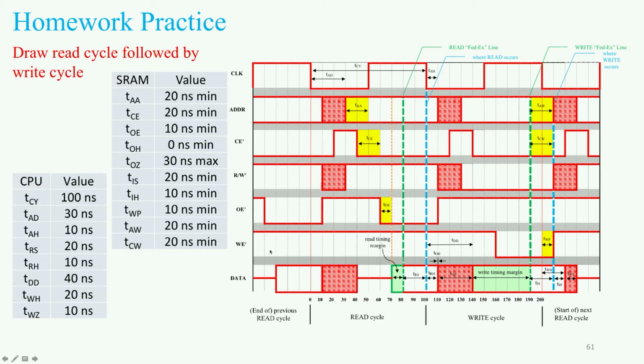Write enable, we're looking at that signal even on the read timing, and so you're not writing anything during this entire phase. So this read-write bit is always going to be in the read state for this first section here. So this bit is always just going to be turned off until we get to the write phase.